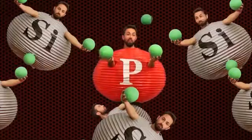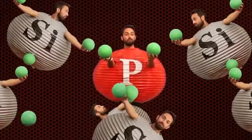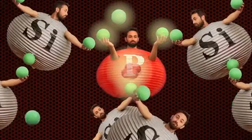And this is why P-type semiconductor is actually called P-type. The P stands for positive. It's positive charges, these holes, which are moving and conducting the current. Now, it's a common misconception that N-type semiconductors are negatively charged and P-type semiconductors are positively charged. That's not true. They are both neutral because they have the same number of electrons and protons inside them.